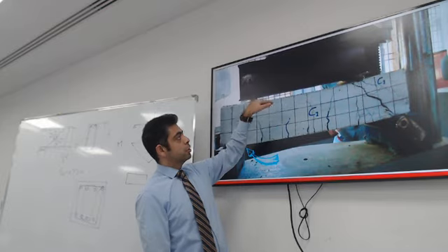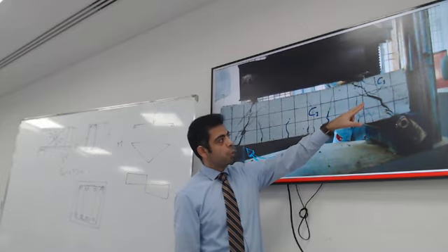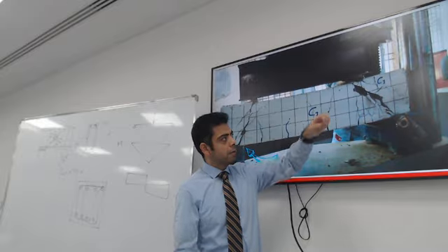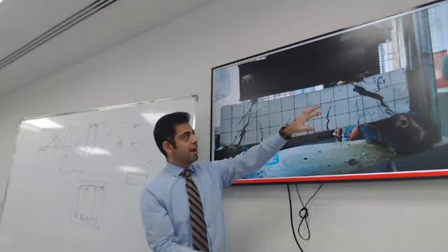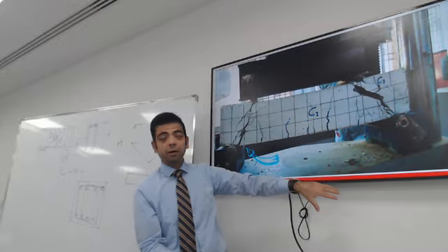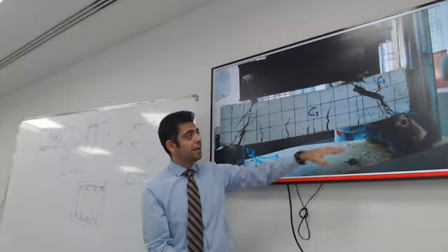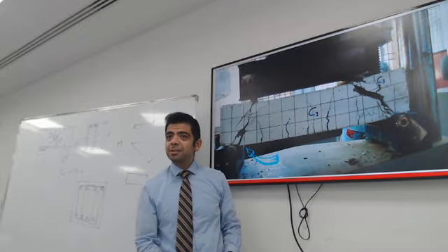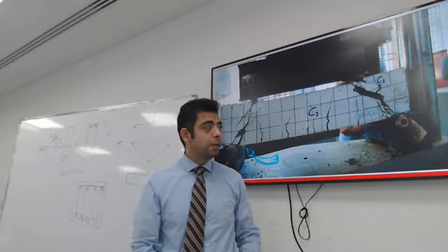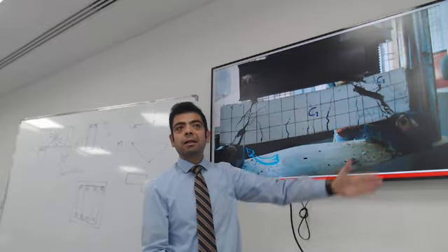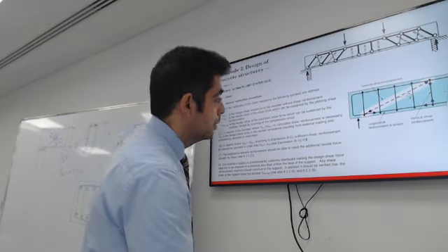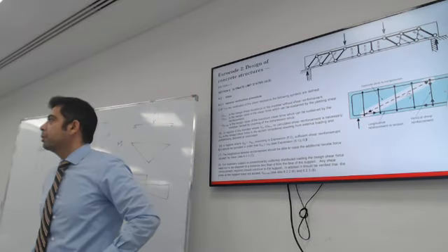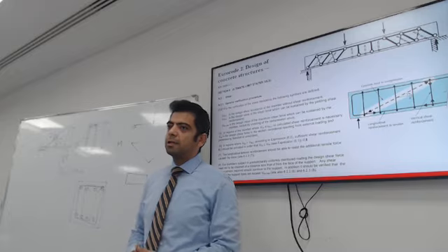As you increase the load, it keeps getting wider and wider until the concrete pretty much falls apart, and the middle part will just fall and crush everyone underneath it, and the top part will follow. It's a catastrophic failure. You don't want your structure to end up looking like this. So it's very important to reinforce for shear design and check for shear design.